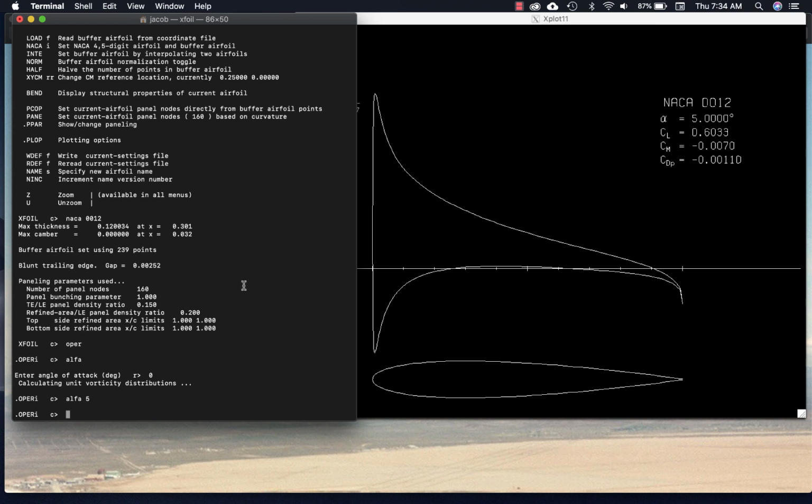Now, obviously, for transition from laminar flow to turbulent flow, you have to have viscous effects turned on. You can think of this in an inviscid flow as essentially always being laminar. Now, interestingly enough, in most calculations where we're going to make assumptions about what the flow looks like, for high Reynolds number applications, we can usually get a good estimate of that by looking at purely inviscid flow. Many of the aircraft we fly today had airfoils that were initially defined using inviscid flow assumptions. You think, wait, no viscosity, that means we're going to have a laminar flow solution.